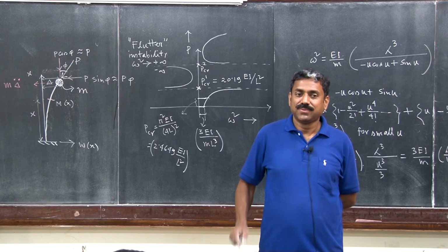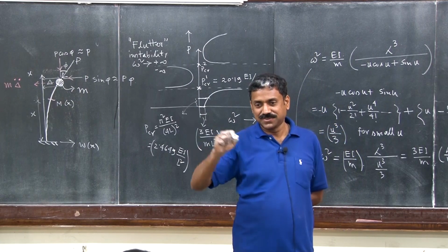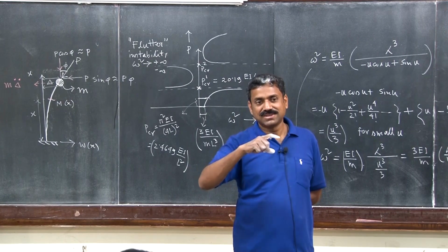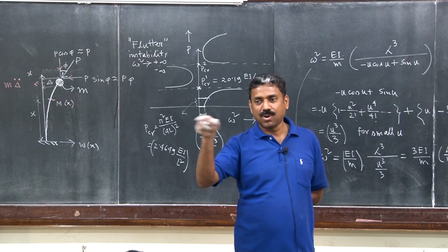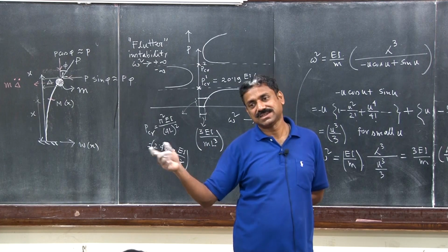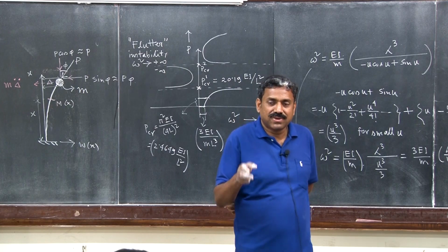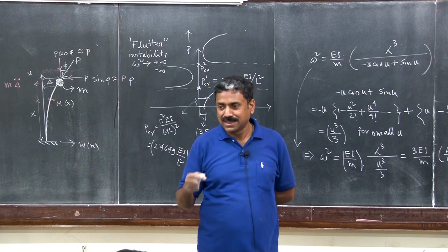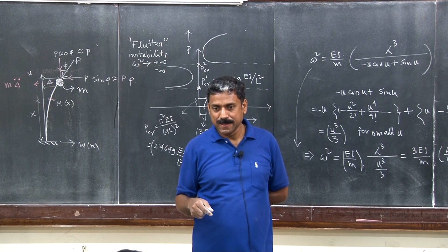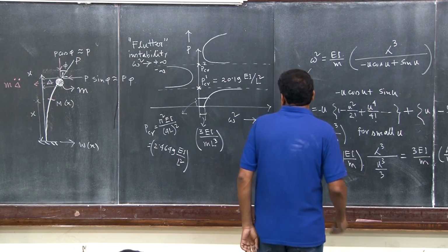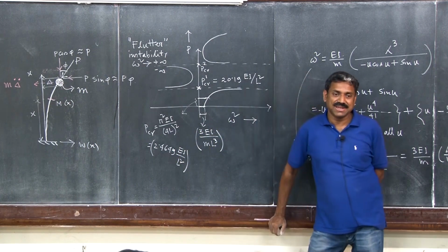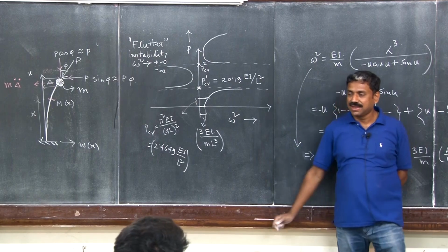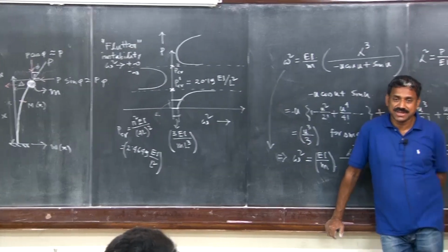And there we have to track the change in frequency with the increasing parameter which is triggering instability. You will see that flutter will be indicated by coalescence and bifurcation of modes. So the real part of frequency will indicate something and it will also be reflected in the imaginary part. Please note that here it is going to infinity because the system does not have any damping. When this is negative, omega will only be imaginary.